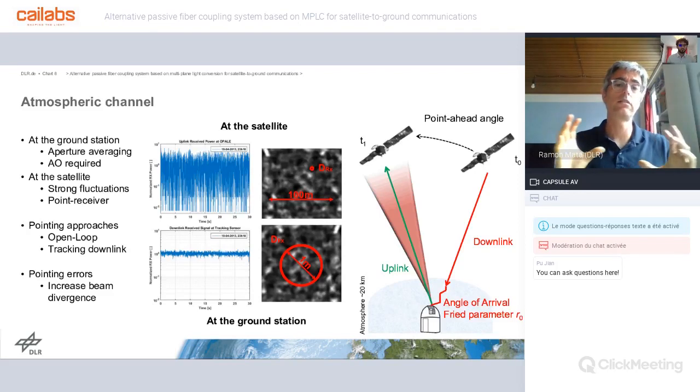The uplink tilt will also move your beam right and left, up and down, producing extra fluctuations. For the downlink, shown in the graph below, the telescope diameter is usually bigger than the speckles, the size of this distortion. So the telescope is averaging the effects, and you receive some light. In the blue signal, you see the variations, but they are much smaller.